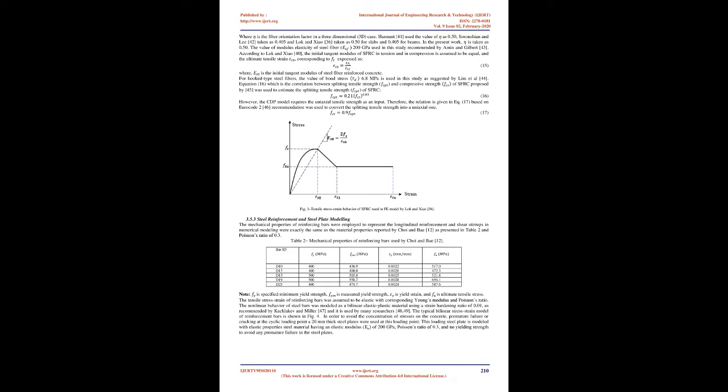3.5 Material modeling. The concrete damaged plasticity, CDP, model available in ABAQUS was adopted for the nonlinear material behavior of steel fiber reinforced concrete in compression and cracking in tension. The CDP model uses the concepts of compressive crushing and tensile cracking to represent the inelastic behaviors of quasi-brittle material. The plasticity of the steel reinforcement and the elastic behavior of the steel plate were considered in the finite element modeling. The CDP model is effective for the analysis of concrete structures under monotonic, cyclic, and dynamic loading 18,19,21. The CDP model was developed by Lubliner et al. 22 and later refined by Lee and Fenves 23.